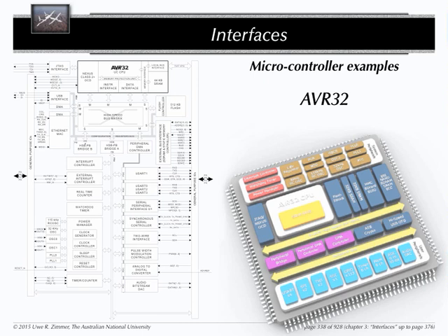And this is more what an actual microcontroller today looks like on the chip. We'll see actual chip photos of more modern microcontrollers later on. You see that the CPU becomes a smaller and smaller component of your microcontroller, which doesn't come very intuitively. Most people think it's basically a CPU which has other stuff around it. It's more a lot of stuff where accidentally you find a CPU somewhere in the middle of it, if you look at the chip these days.